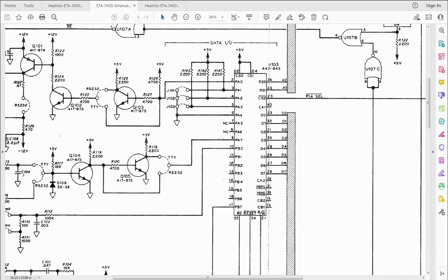On the other hand, the terminal, which is the other side, sends bit streams back to this, which in this case are received on pin PA7, which is configured as an input. And all this does is it reads the state of what's coming in. So the processor again has to sit there, read what's coming in on here, figure out how to sync this, basically sitting there waiting for a start bit.